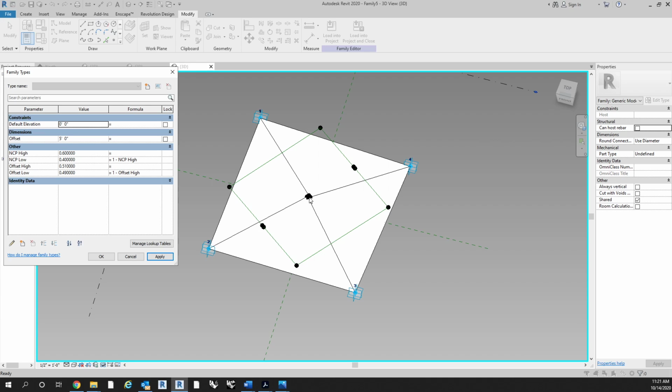We could set up an if-then statement in this family type, and I'll go over that a little bit later in the semester. But all we need to know is that we can't have 0.5 or lower. When we set up our parametric scripts and revalue the parameters we're playing with, this value can only be 0.501 or whatever, and greater, up to 1. You've got to keep that in the back of your head: you can't set this specific parameter anywhere lower than 0.5.